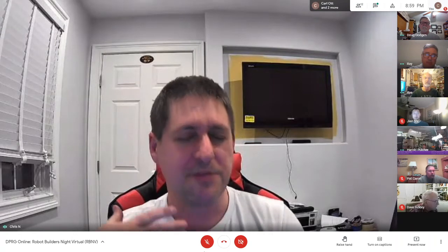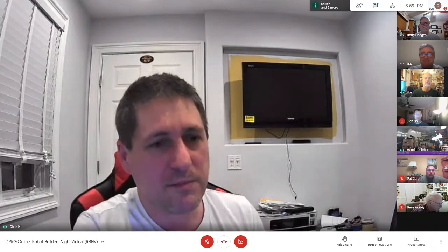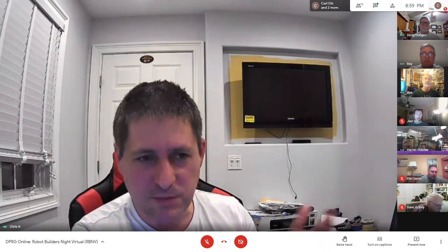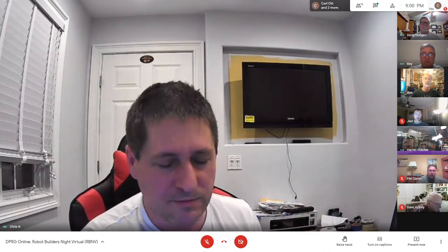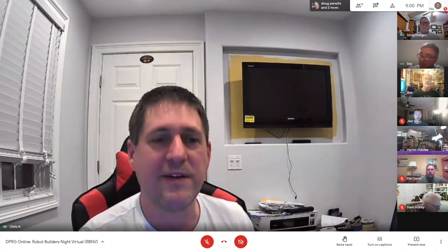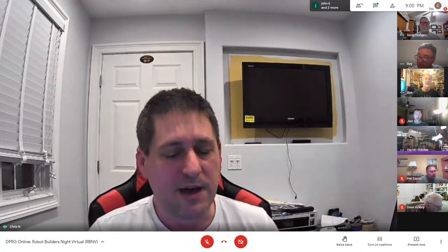Well, that's a good number to know. So however it's done, if we can stay at 100 milliseconds, that's a reasonable control rate for a slow robot. Yeah, it's a subjective thing, right? I think you have to train yourself to deal with that delay. When I'm remote controlling my Romy here, with no video at all in the loop, just me pressing a button and looking at the Romy, there's practically no delay, instantaneous feedback. You can zip it around pretty fast. As you add delay, you just have to train your brain to deal with that. That's the bottom line.